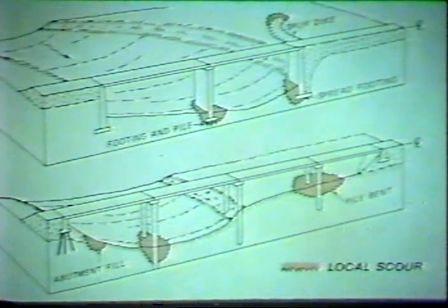Local scour was identified only at those sites where scour was known to be localized at a pier, abutment, or other obstruction to flow. Its effects are superimposed on those of general scour, and it probably occurs during every flood when measurement is difficult. Local scour is attributed to diving currents or to eddy action at an obstruction to flow.